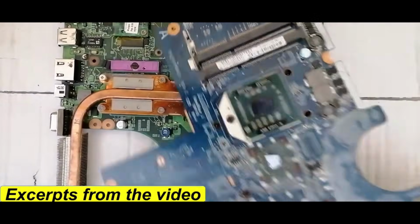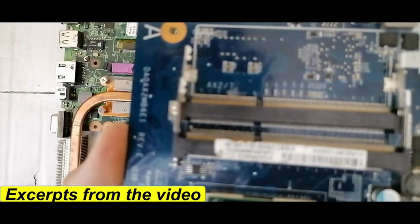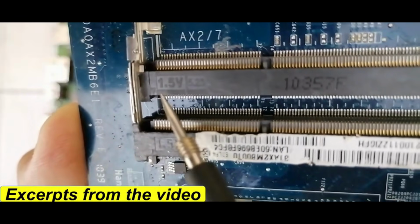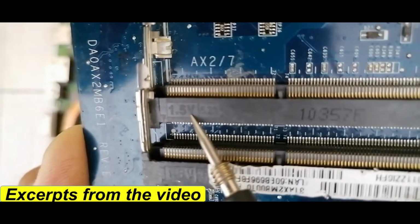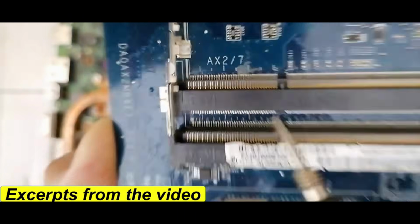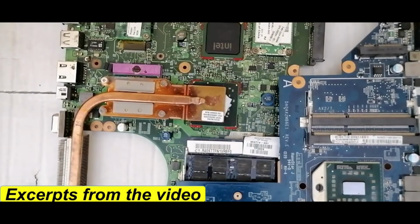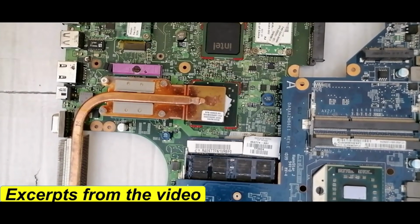I will show you another motherboard, for example this one. Let's see the slot of this motherboard. As you can see over here, we have 1.5 volts, the voltage for RAM in this motherboard, which means this is DDR3. So based on the voltage, we identify whether the RAM is DDR1, DDR2, DDR3, DDR4 or DDR5.